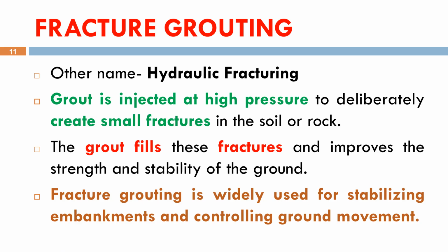Now let's discuss fracture grouting, which is also known as hydraulic fracturing. In this method, grout is injected into the ground at a pressure high enough to create small fractures in weak soil or rock. The grout then fills these fractures and hardens, forming a stronger and more stable ground mass.